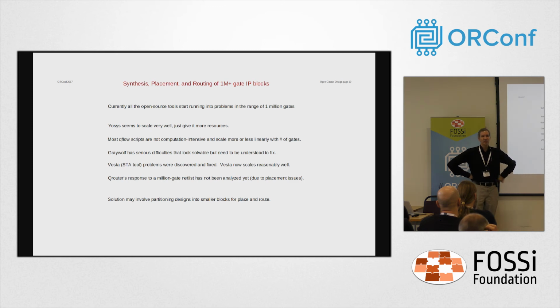That pretty much limits you to processes that are above 90 nanometers, which on the whole, I think a lot of the other tools are going to start failing for other reasons when you get below 90 nanometers. For instance, QRouter just is not going to be able to know all the DRC rules that are prevalent when you get down, particularly right around 45 or so. You get all these optical design rules that are requiring you not to do certain run lengths. That's where the same sort of thing would come in for the parasitic extraction, and I think those are all going to have to be solved at the same time.